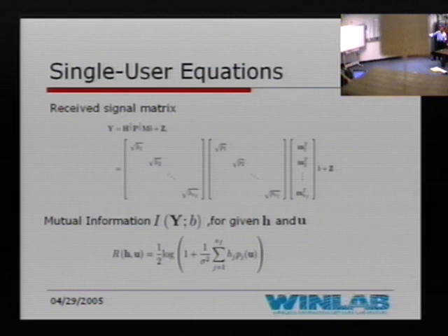Well, this model essentially is parallel subcarriers. But coming back to your question, in recent years there has been a lot of research on how to find basis functions for doubly dispersive channels. They show that if we use signaling via them, even a doubly dispersive channel may be looked upon as a block fading model. This is basically a baseband model; I haven't talked about the modulation studies.